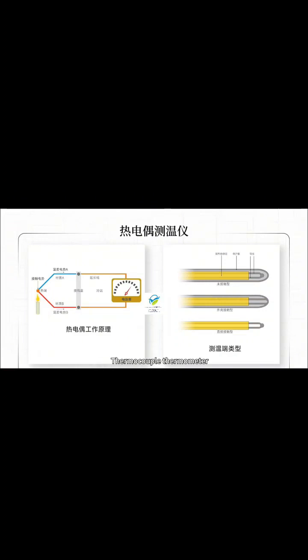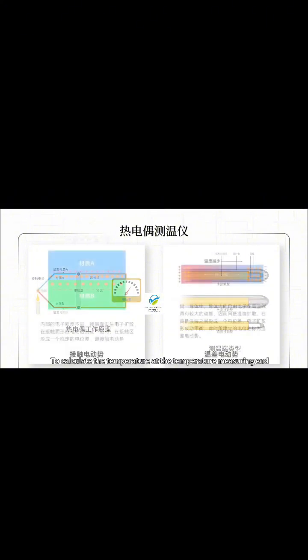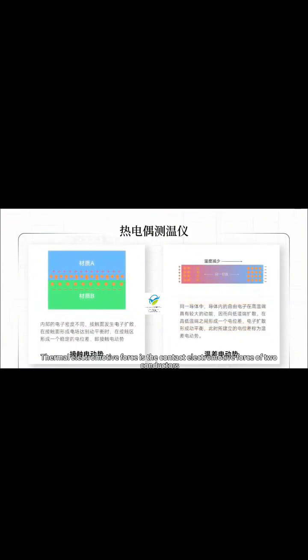Pressure thermometers also use the principle of heating and expansion of working liquids or gases, store them in the instrument, and combine the temperature pack with a spring tube. When the working fluid inside the chamber is heated and expands, the spring tube is driven to deform to indicate the temperature. The interior is similar to that of a spring tube pressure gauge. The overall structure is simple, the measurement range is wide, the temperature sensing is relatively sensitive, the accuracy is moderate, and the price will be slightly higher.